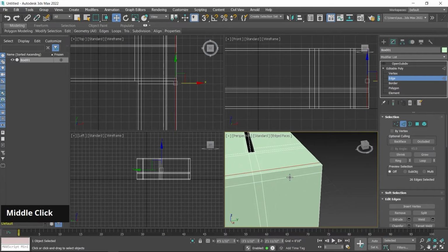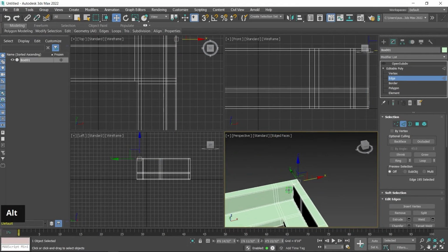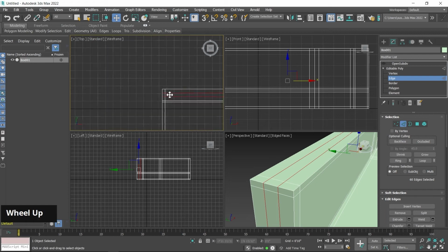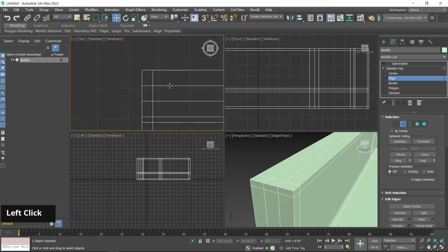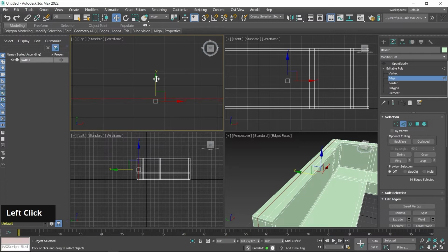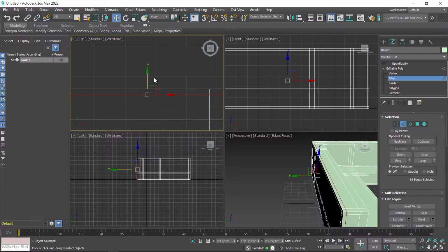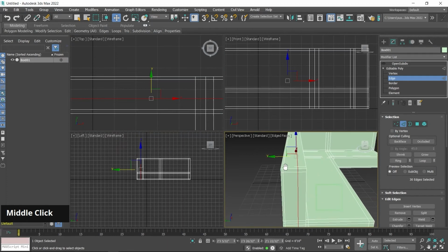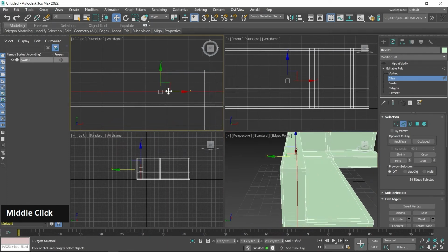Same as you can create two connection for this side also. Yes, select this edge. Okay. You can select this edge from this face by clicking. Click on the ring selection, right click, connect. Okay, two connections are created. By click outside I deselect this, then double click for selecting this edge, and then use top viewport for moving. Okay, if you are using this top viewport, you have better control for move this edge. Same as I select this edge by double click and then move nearby this edge.